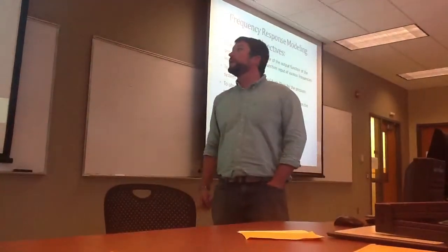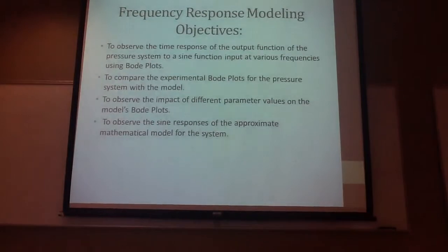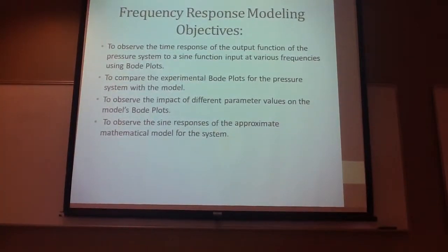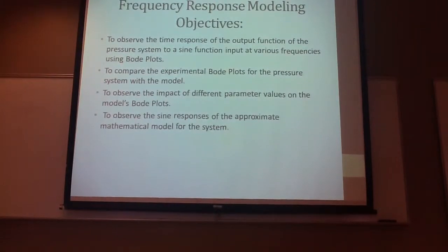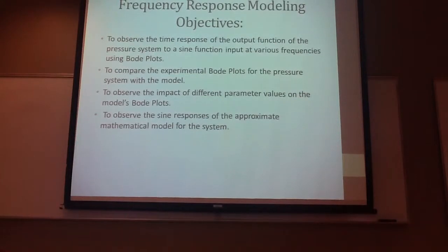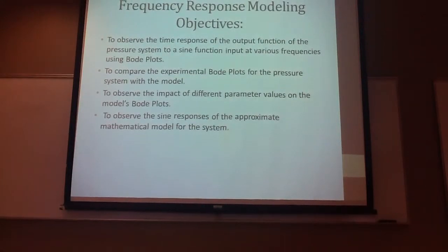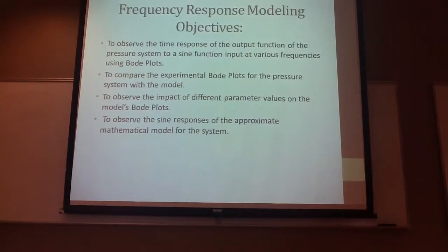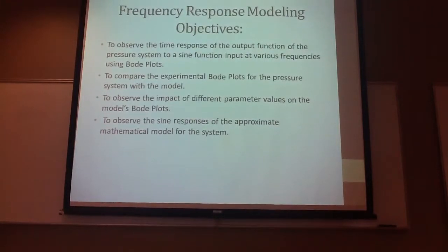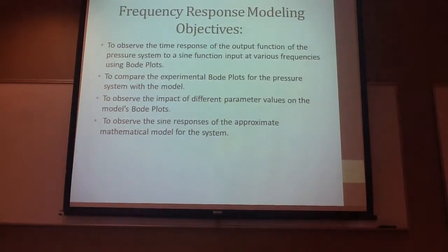For this week, we're doing frequency response. A few objectives are to observe the time response of the output function of the pressure system to the sine function input at various frequencies, and then use Bode plots to compare. It's also used to observe the impact of different parameter values on the Bode plots, and to observe the sine responses of the approximate mathematical model for the system.